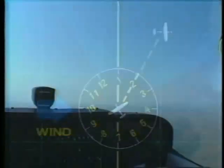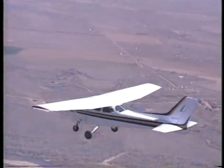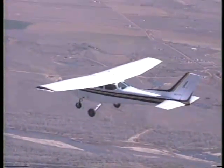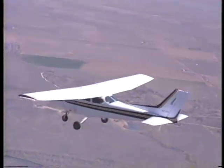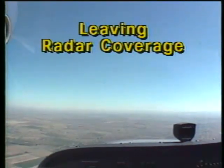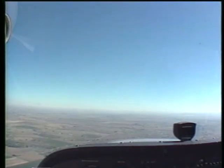Let the controller know whether or not you have spotted the traffic. If you don't see the traffic, tell the controller negative contact and continue to look. Keep in mind that traffic advisories do not relieve you of the responsibility of maintaining your normal scan for collision avoidance. When you leave the radar coverage area, the controller will let you know that the service is no longer being provided and will have you reset your transponder for VFR flight. "Cessna 740, radar service terminated. Resume your own navigation, squawk 1200."